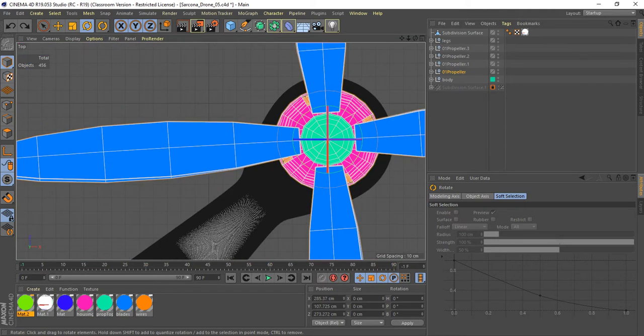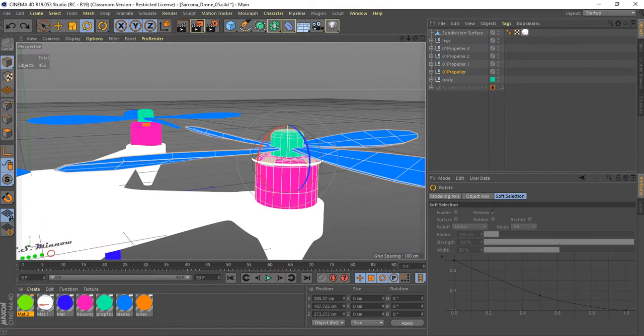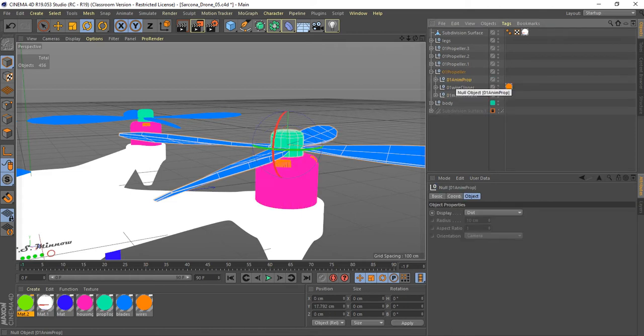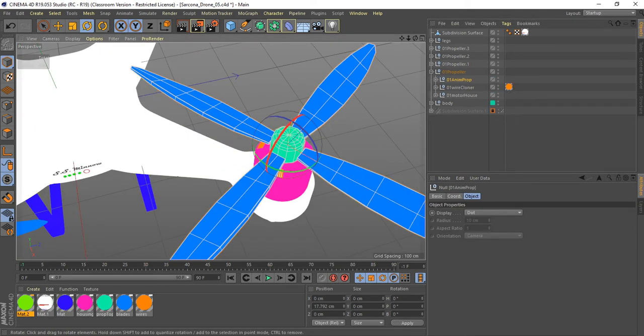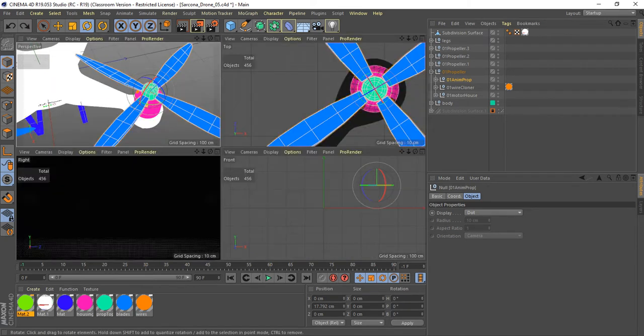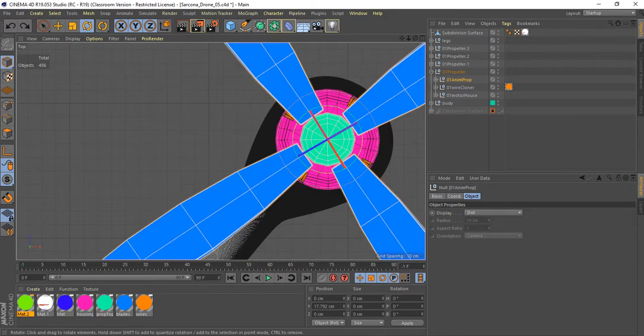Now, as I'm rotating this around, I don't know if you caught it already, but I'm actually grabbing the entire thing, which is the housing too. The housing does not move. It's literally just the cyan part and just this blue part. So I need to make sure that I go into this animation prop area, and that's the part that I should be rotating around. And yep, that definitely looks like it's good. And again, I will verify it in the top view. And yep, that is definitely working correctly.